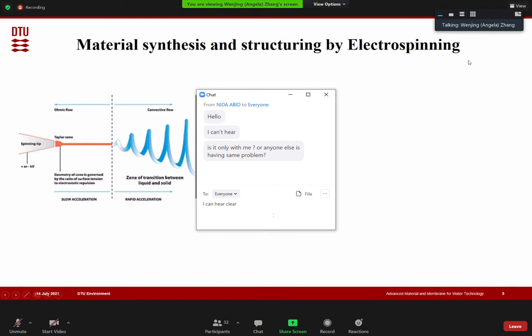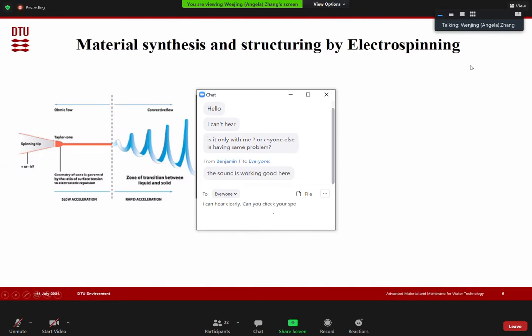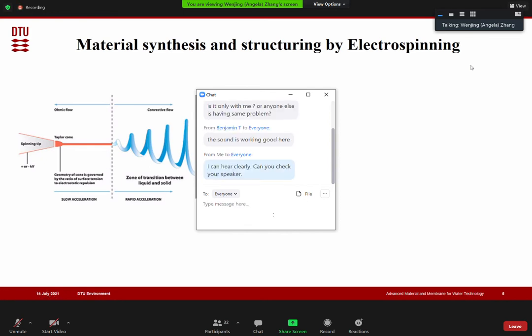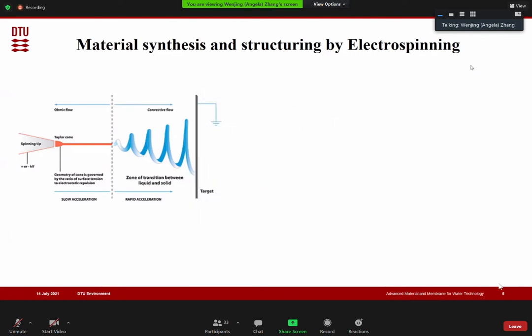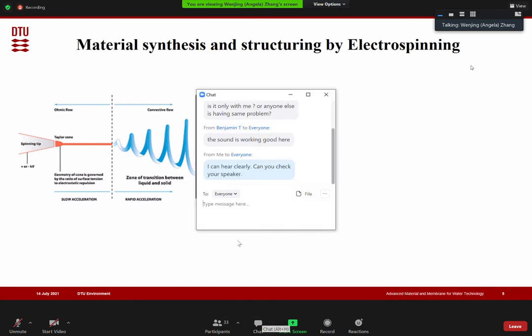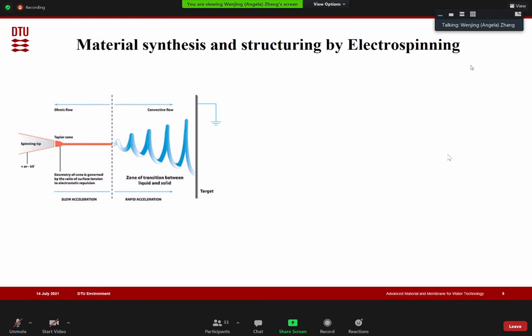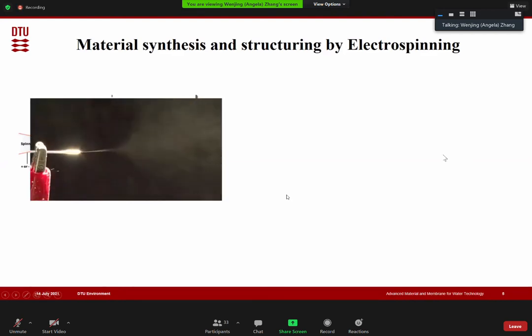And what you do is you often start with a polymer solution, about 5 to 15 weight%, and then you push it through metal needles. And this needle will form droplets at the end. If you apply the voltage, they will generate electrostatic force and elongate these droplets of polymer solution into a nanofiber. So one sees it is quite slow, but if we put it in motion, you can see it's very efficient.